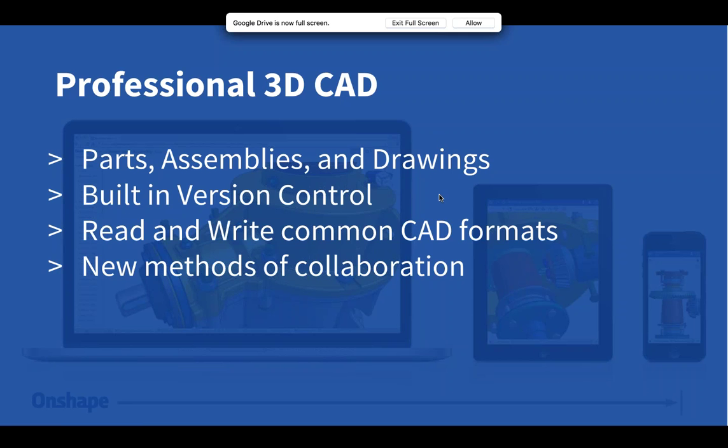Also with Onshape comes the ability to both import and export common CAD formats. So if you've come from a traditional CAD system, or if you've come from some other CAD system and you have this library of data, chances are we can import those CAD files. Some examples would be Step, IGES, Parasolid, SolidWorks, Inventor, Creo, CATIA, a number of different formats that we can import. And many of those we can also export. So this makes it a great tool for importing and storing your CAD data, maybe collaborating with others, a great tool to work alongside an existing CAD system.